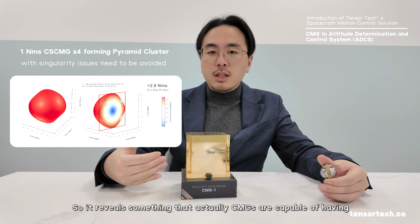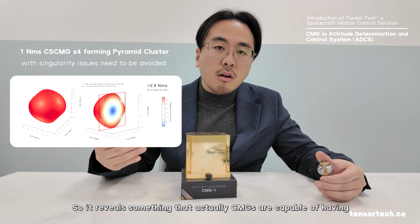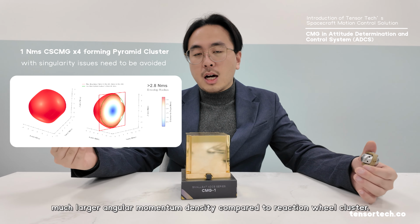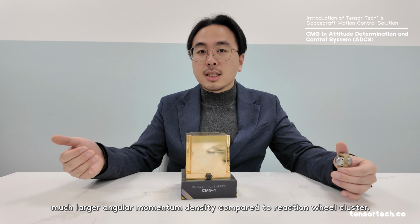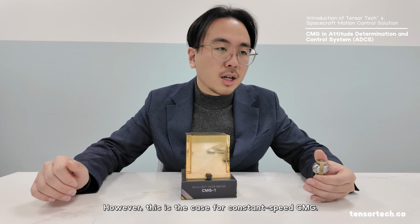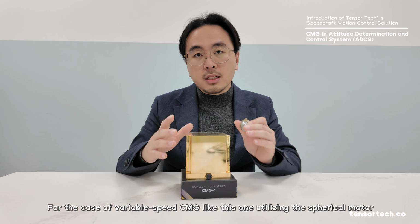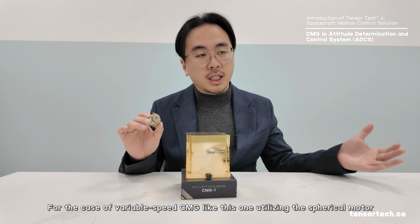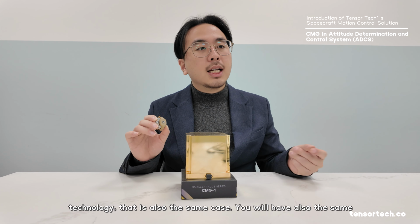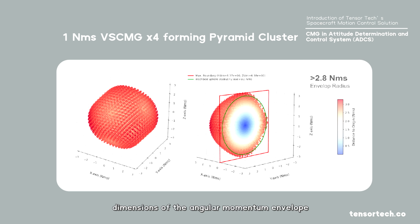So it reveals that CMGs are capable of having a much larger angular momentum density compared to a reaction wheel cluster. However, this is the case for constant speed CMG. For a variable speed CMG like this one that utilizes spherical motor technology, it is also the same case: you have the same dimension of the angular momentum envelope for this pyramid cluster.